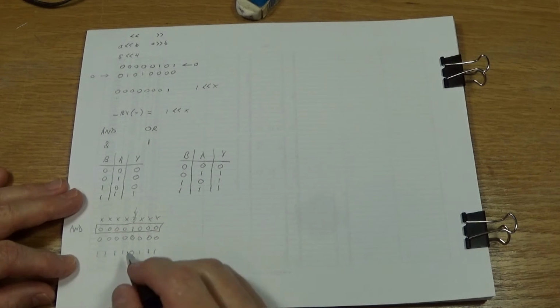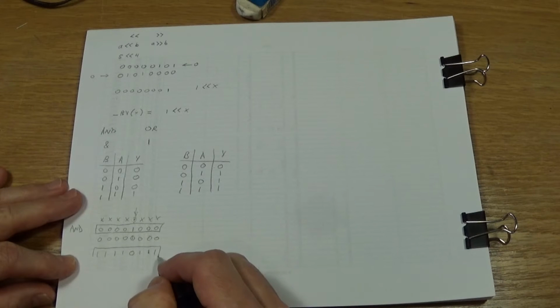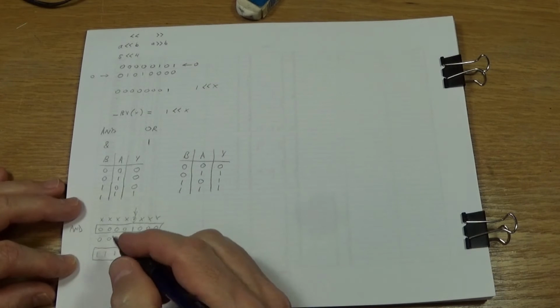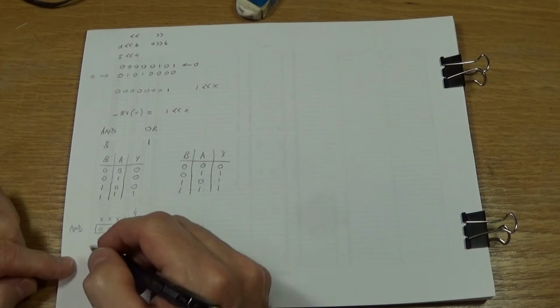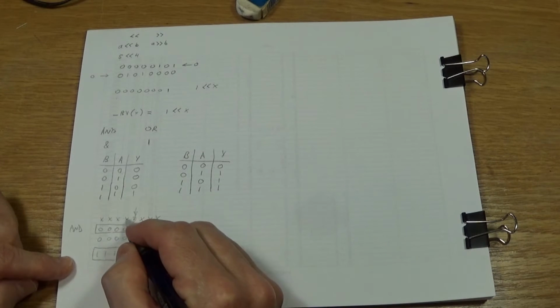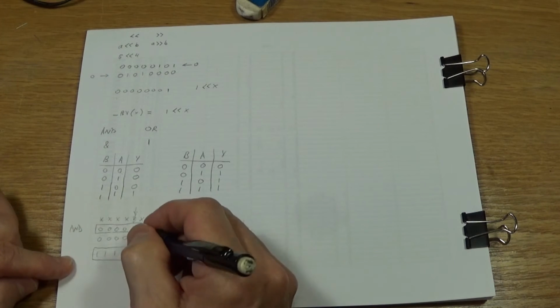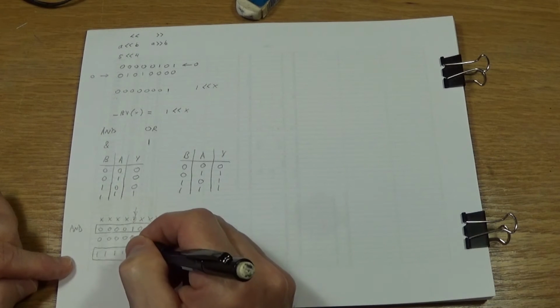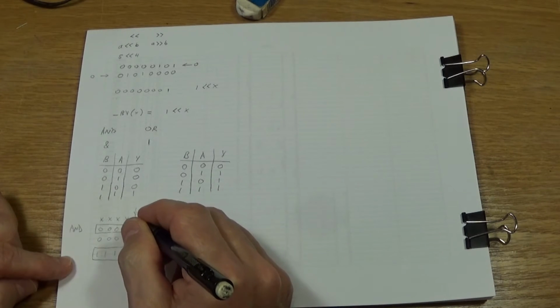So when you AND this mask, this is another mask, and I'll be using this a lot, with our register, and put the results of that ANDing back into that register. Wherever we get a 1 here, whatever the value that was in the register will remain the same. If this was a 1, 1 and a 1 is a 1. But if this was a 0, 1 and a 0 is a 0. So this result is never changed. But when we get over to this bit here, we've got a 0. A 0 with anything, 1 or a 0, will always produce a 0. And so this bit will always get cleared.